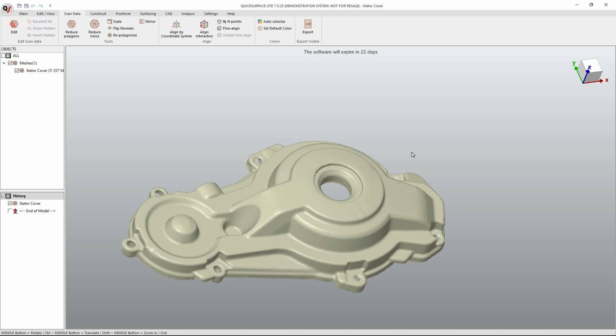when we go from our scan data, because sometimes if we don't capture enough points in a certain area, when it goes through the process of turning it into a mesh, we end up with those holes, and it's kind of too late. We need to fix them either in RevoScan or the Creality scan software, or whatever scanner you're using, and then we need to go into another piece of software like this, QuickSurface LITE.